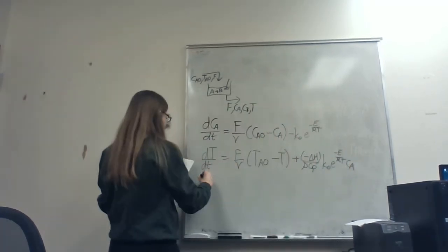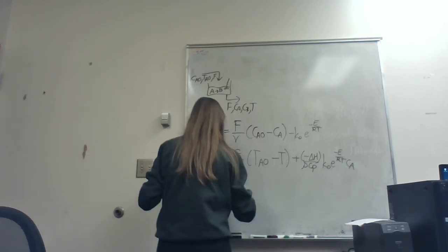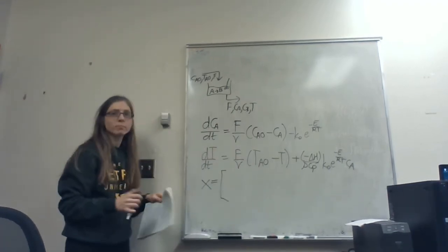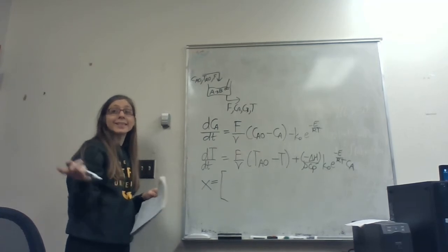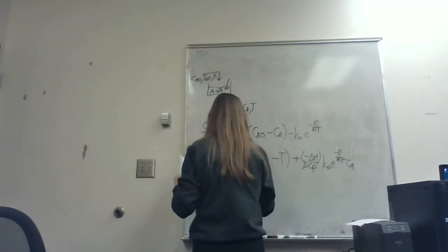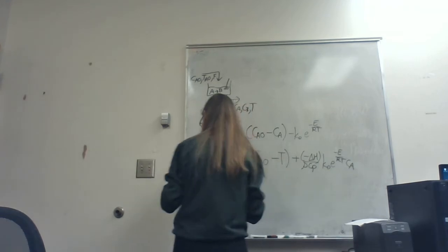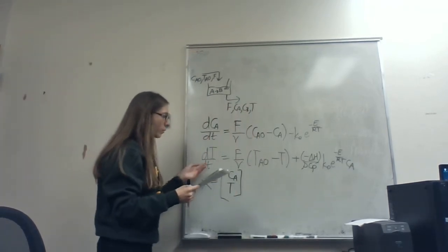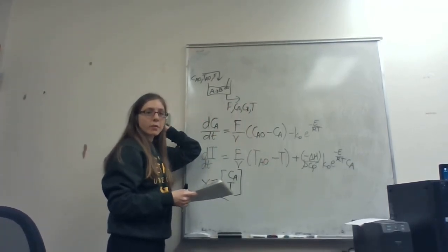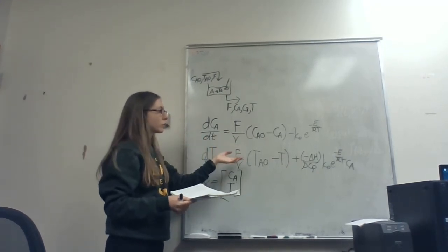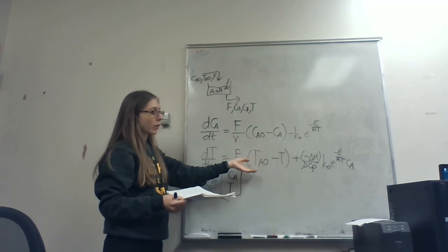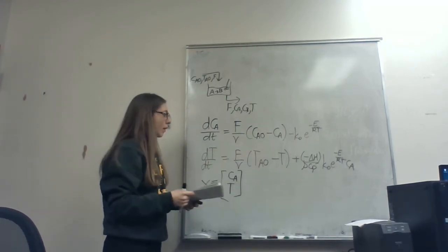But already we have this nonlinear system where our states, what would the states be here? Temperature and concentration. Exactly. Great job. C_A and T. And then we can select some of these to be inputs. Input selection is part of control design, where you choose what's available for you to manipulate and whether you're going to manipulate it or not.